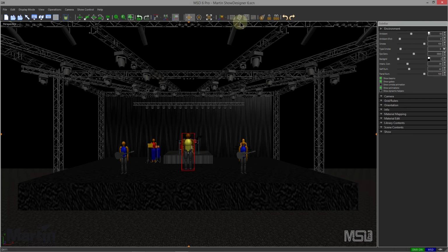The next icons here are the grouping operation. So if I select two objects here, this will group them together, and this one here will ungroup. As you see, there's a G shortcut for grouping and a U for undo grouping. This one here is grouping according to the axis of the red object. So this is useful when this object will become the center of rotation of that group. So if I do this here and try to rotate this object here, you'll see this person here becomes the center of rotation of the group.